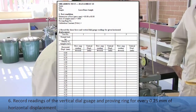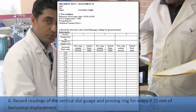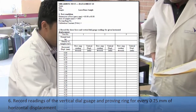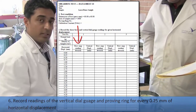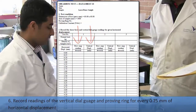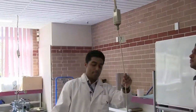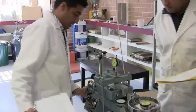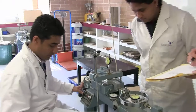There should be 3 students. One should be reading the vertical displacement gauge and tell the other 2 students when to take down the readings, and one of the students can take down the proving ring reading, and the other student take down the vertical displacement reading. So once everything is set up, you just make sure the power is on and switch on the machine.